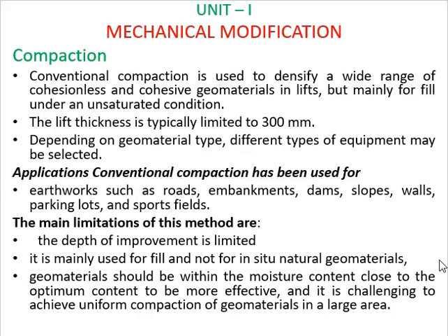So the main limitations of this method are the depth of the improvement is limited. For compacting the thick deposits of loosely filled soils, it is not an effective method. So it is mainly used for compacting the new layers of soil above the existing ground and not effective for in situ natural deposits of soil.